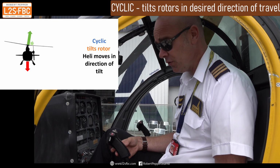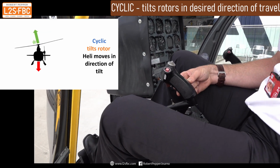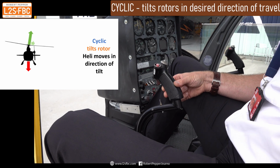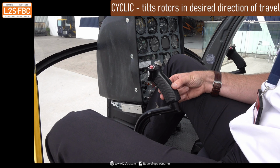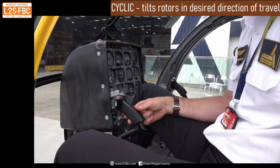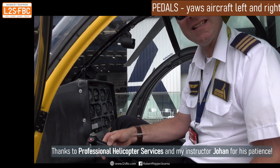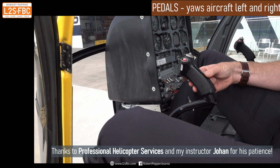The cyclic also controls our lateral directional control. Cyclic left, the disc will tilt left, and as such the machine will start turning left. Opposite with right, and you can make a combined input. It's a misconception that people think you first have to apply forward and then left. That is not true. You can actually put inputs through the entire cycle, and hence its name, cyclic.